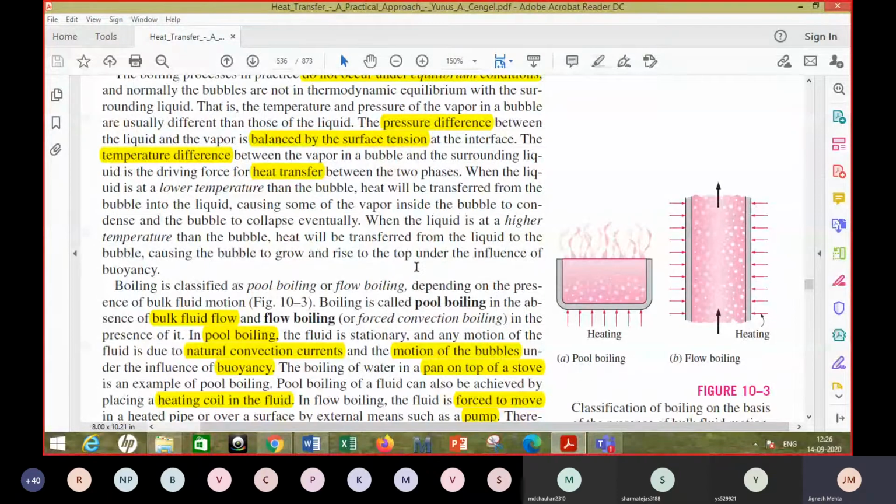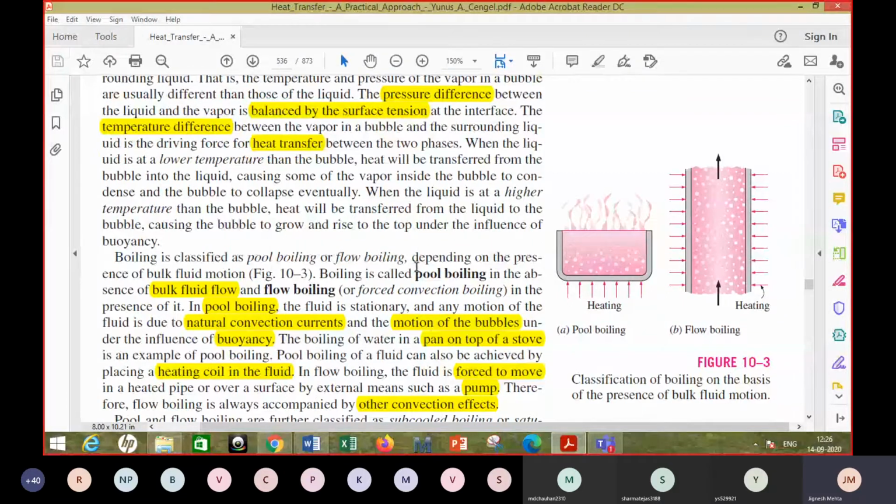So the evaporator coil that is there inside the room, right, there is a boiling of refrigerant occurring inside the tube. Of course, you can't see it, but you call it an evaporator, but actually it's boiling, not evaporation. And then condenser outside. So there is a conversion from vapor to liquid by rejecting heat to air, and the refrigerant is condensing there.